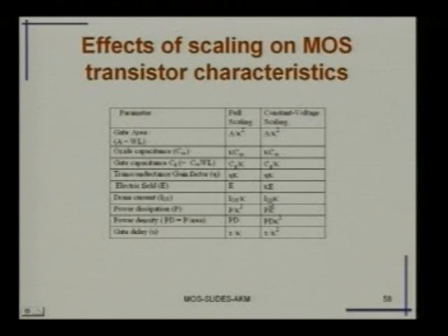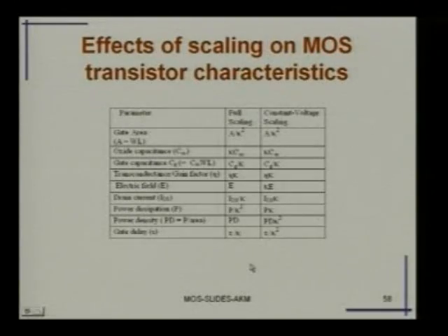So, one issue will be therefore that with full scaling, you reduce the power dissipation, but the gate delay, which is used for the switching characteristics, that is how much input output delay, will also reduce. So, the technology today is accompanied by the reduction in the sizes of the transistor together with the electric field and all the other characteristics. And why? So, the equations that we have derived somehow give you an idea of what happens.